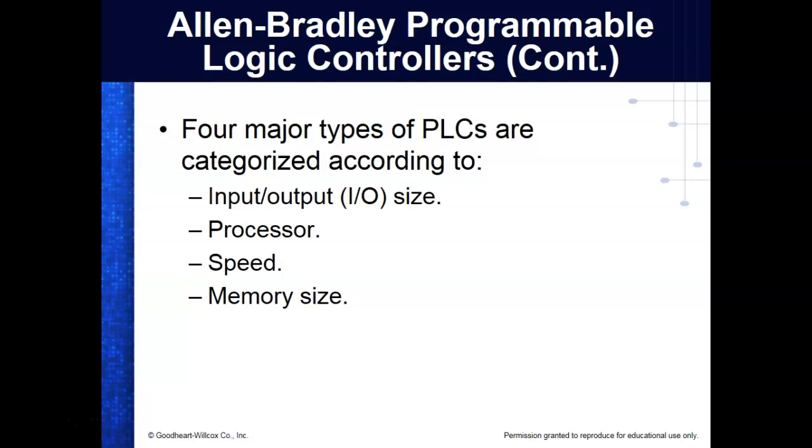So you buy them according to the inputs and outputs. Sinking inputs, sourcing outputs. We need to understand that. Predominantly here in the U.S., we use sinking inputs and sourcing outputs. We'll talk about what it means. That's predominant. Some PLCs give you the ability to wire either way.